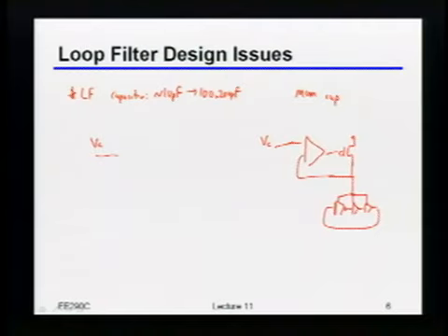Well, now I know that this control voltage here is going to have to be at some reasonably positive point, because otherwise my ring oscillator is going ridiculously slow, right? So that means that I can kind of guarantee that there should be some reasonable bias, which means that I can probably get away with actually putting a MOS cap there, okay? So just as an example, you might build that as something like this, okay?